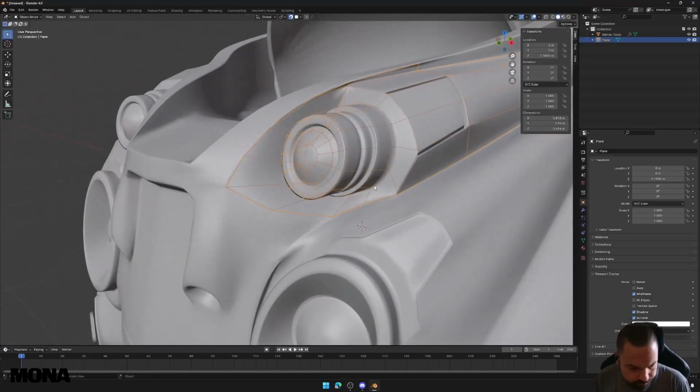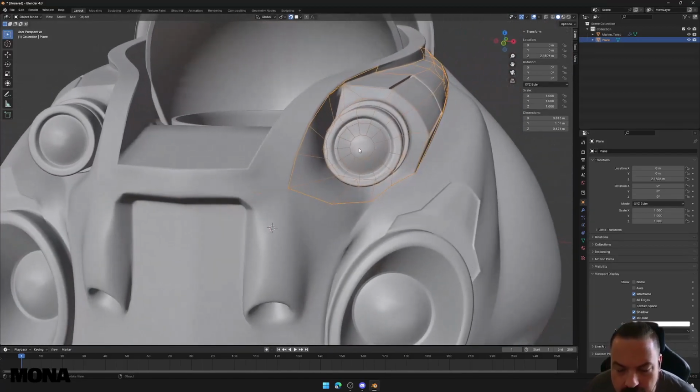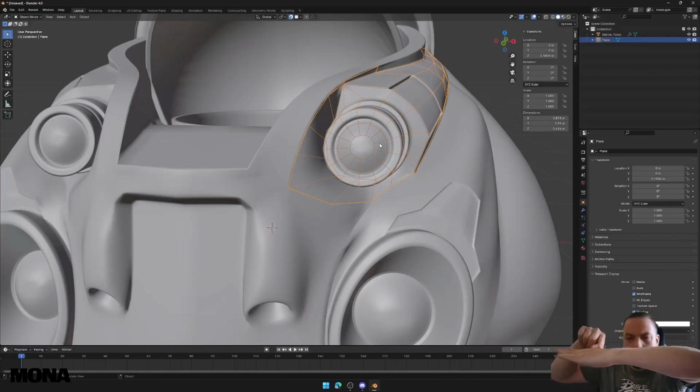So baking, and this comes into the big baking thing. Baking creates high polygon information on the texture. The simple version is bump map, but unfortunately a long time ago, bump maps were literally like grayscale up and down. Normal maps have a little more control and complexity. So basically, if you have a flat polygon across there, right?